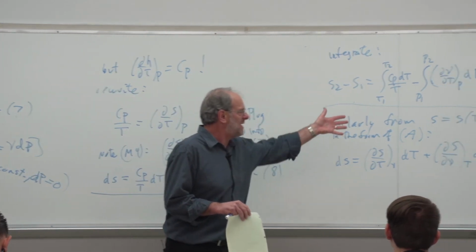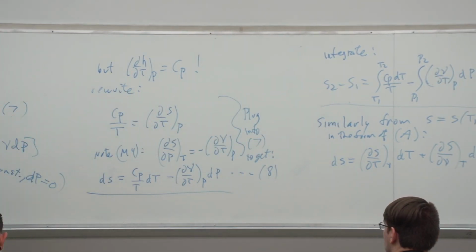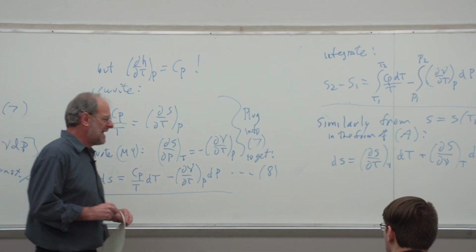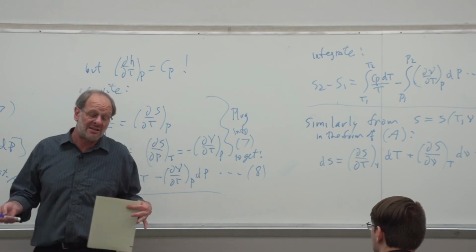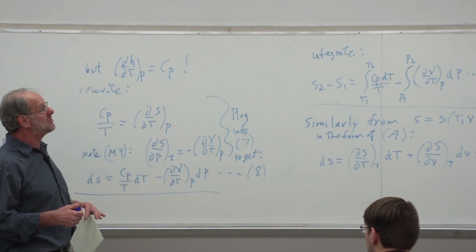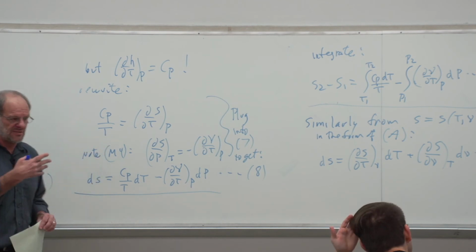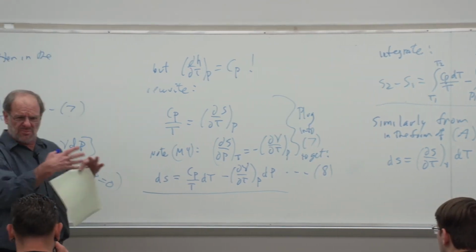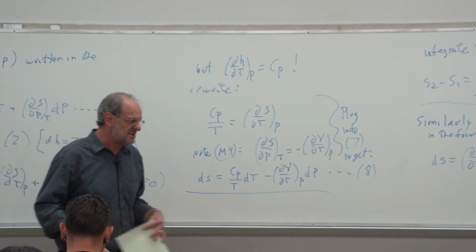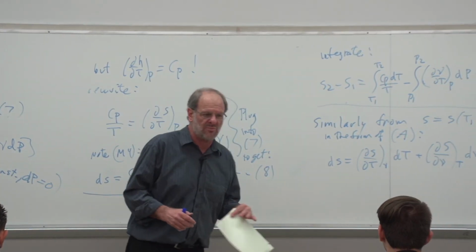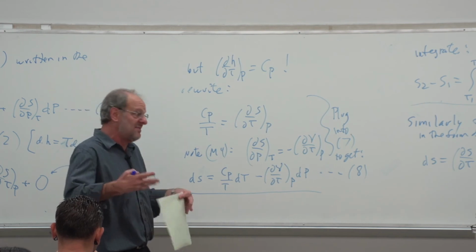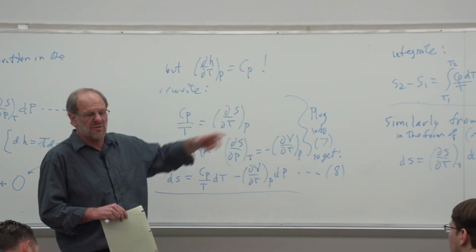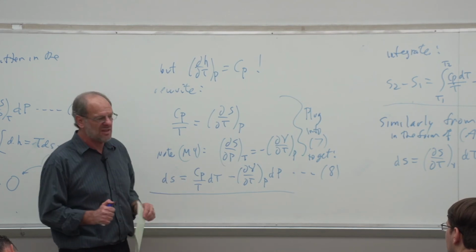So I guess you could say in many ways that a lot of this is just illustrative of the kinds of derivations and analysis that one would do in the research world. But no, we don't have good data in our tables to do a good bounding analysis with Cp and Cv available. If you had to, table A-2 part C gives you Cp as a function of temperature, and it's a polynomial equation, and it's on a molar basis, so it's really Cp bar. You're going to have to divide out the molar mass to get Cp, and then relate Cp and Cv through the gas constant. Cp minus Cv equals the gas constant, and it just becomes a kind of a mess to do all that integration. So I'm not going to give you anything like that.